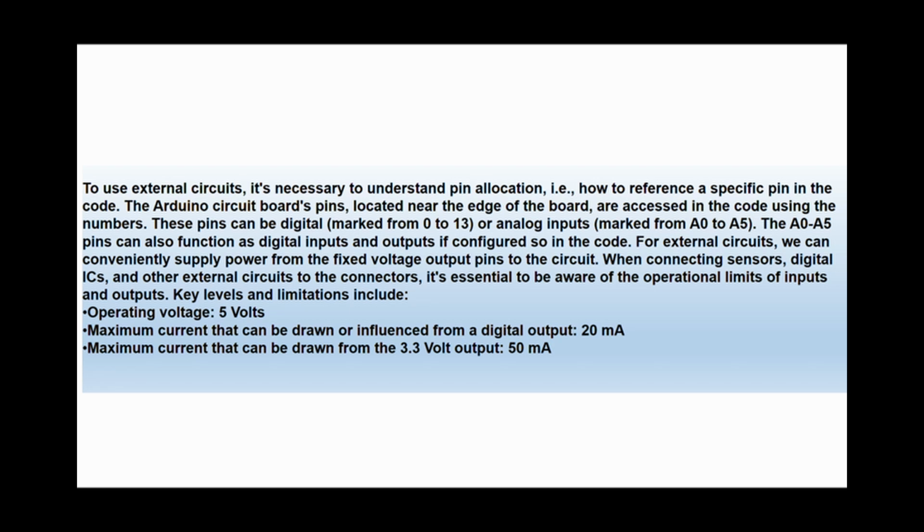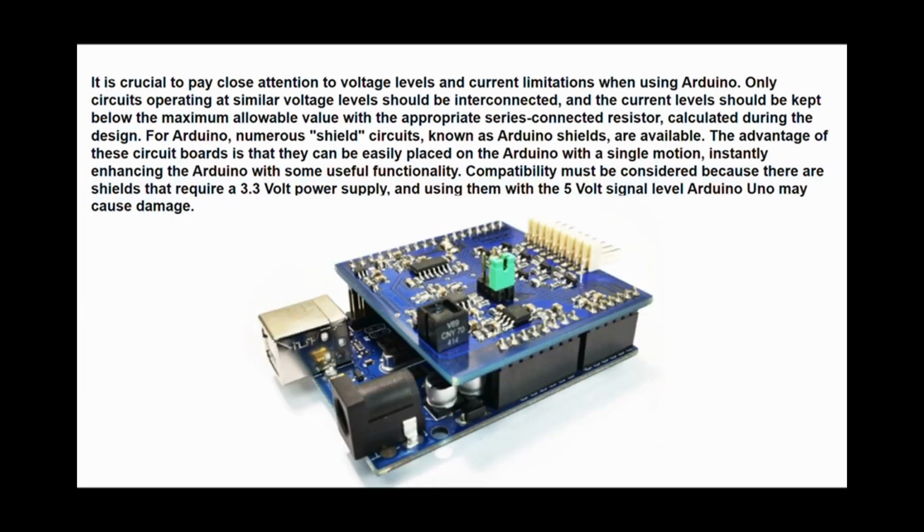It is crucial to pay close attention to voltage levels and current limitations when using Arduino. Only circuits operating at similar voltage levels should be interconnected, and the current levels should be kept below the maximum allowable value with the appropriate series-connected resistor, calculated during the design.